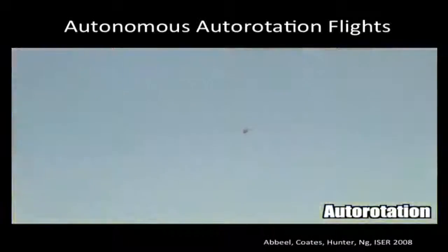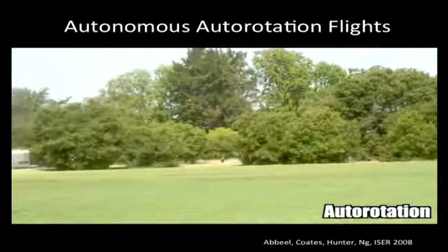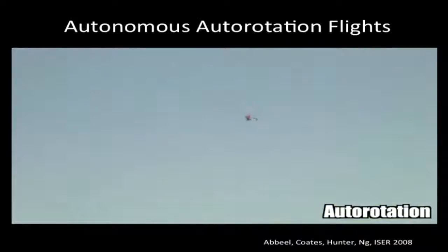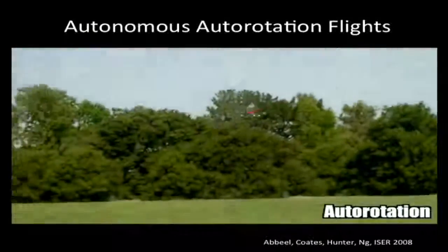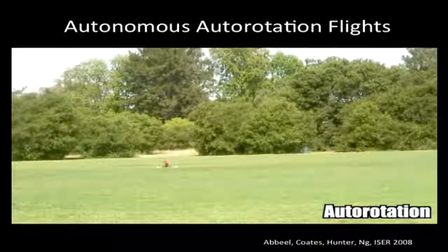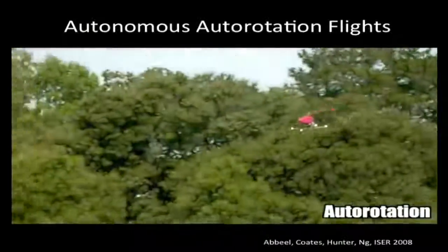You have energy because you're high up. You have the engine off, so the blades will not be automatically propelled. You can control the helicopter to capture that potential energy into kinetic energy of the blades rather than kinetic energy of the body of the helicopter going down. When you have the kinetic energy in the blades, then once you're close to the ground, you can change the angle of attack of the blades, generate a strong downward thrust to slow it down and land safely.